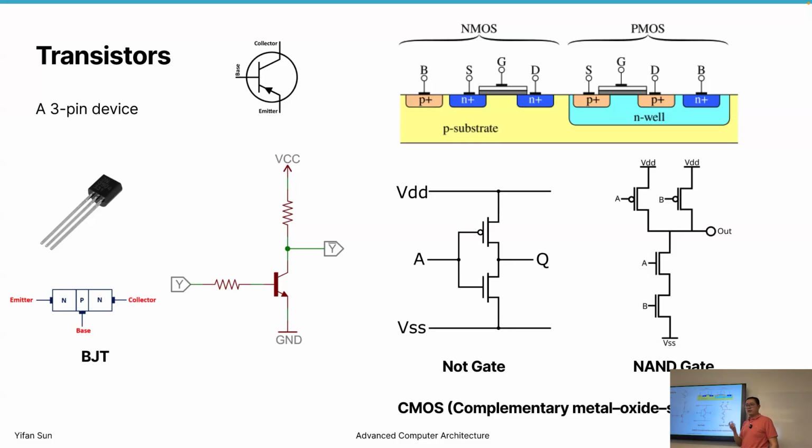So what's the energy consumption? Typically, we say a chip consumes two parts of energy. One is dynamic energy, one is static energy. Static energy means there's no pure isolation, right? There's always some voltage, some electrons going from VSS to VDD. The current goes the other way. But in CMOS, this is really small. And no matter whether it's 1 or 0, it's still that small.